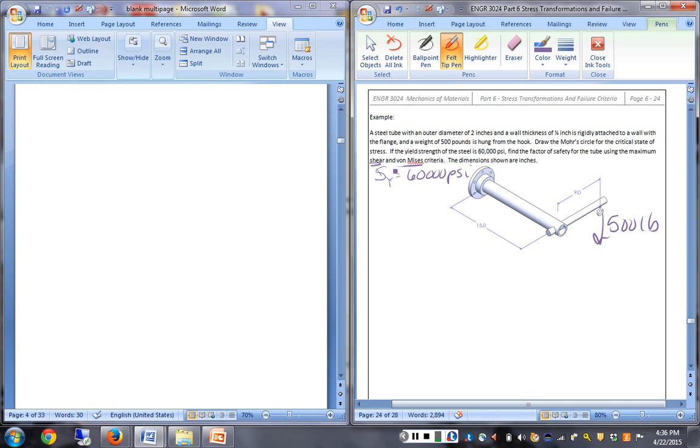Different circle. The shear stresses from the torsion do this. The shear stresses from the linear force do that. So if the shear is not negligible, it'll be here at 3 o'clock.